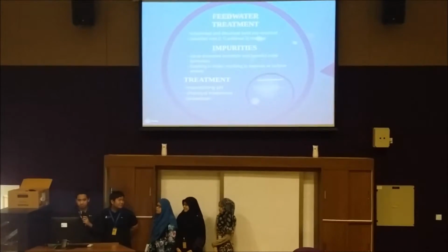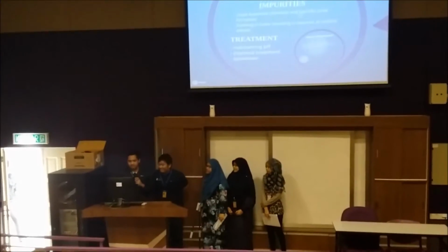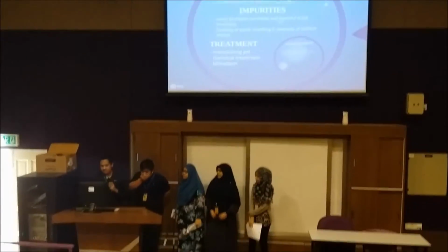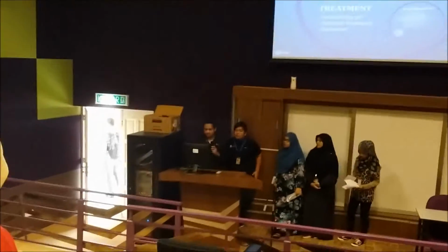Today we are going to present chapter 4 about boiler operation and maintenance. Firstly, before that, the boiler prime mover is water. Therefore, it must be treated first. Why must it be treated? To remove suspended and dissolved solids. It's classified into two: external and internal.